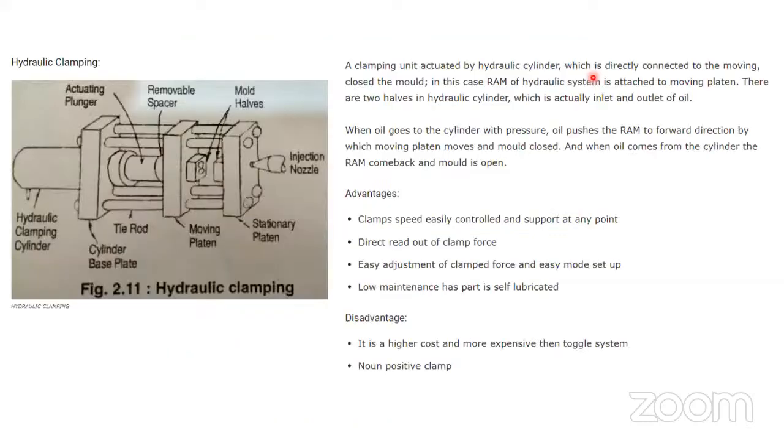Now, then they developed these toggle systems, single toggle, double toggle. It is not working properly. There are many drawbacks. Cycle time is also high, and you will not get a proper article, or you cannot measure the clamping force, friend. Now, see here, in this case, the clamping pressure you can measure here, friend.